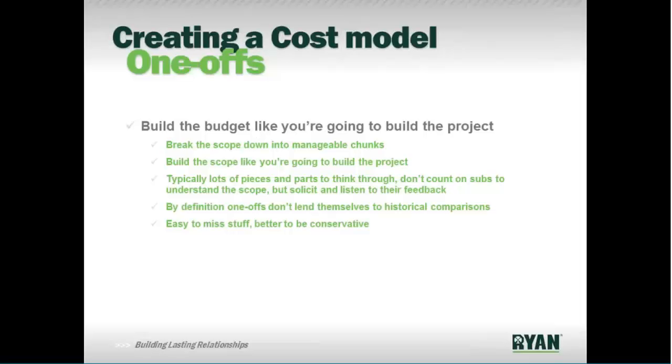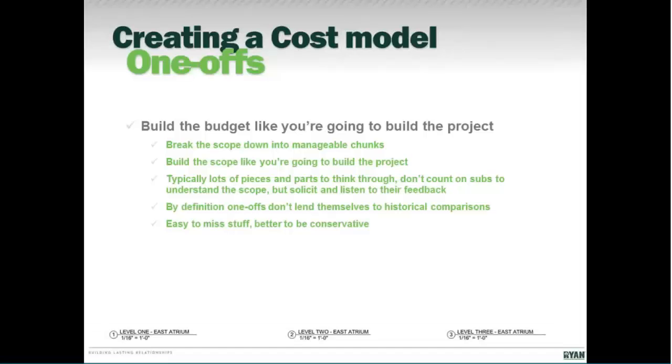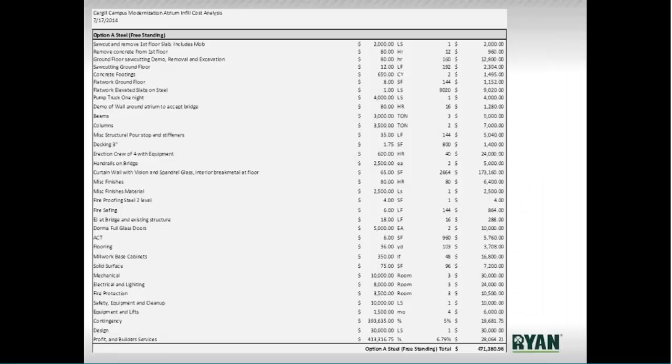And what I would typically recommend is that you just start from day one. You're showing up on the job. What are you going to do? You've got to create access into the building. You've got some demo to do within it. You've got some structure to build within this new conference floor. You've got to figure out how to get your concrete in. And you've got to figure out how to get your steel in, and how much steel do you need, and just thinking through that process of how you're going to build it. And then your budget should more or less just reflect that.